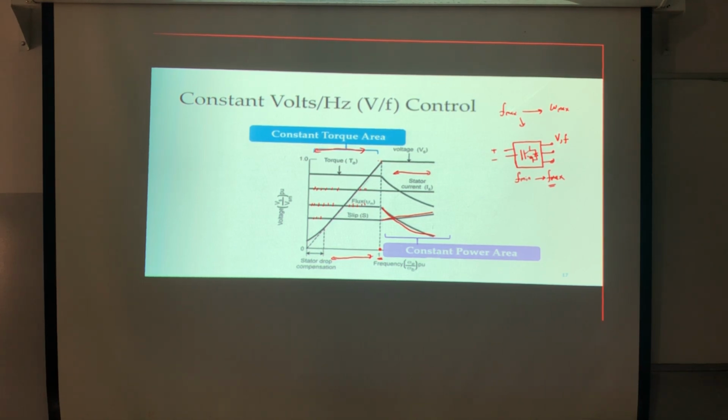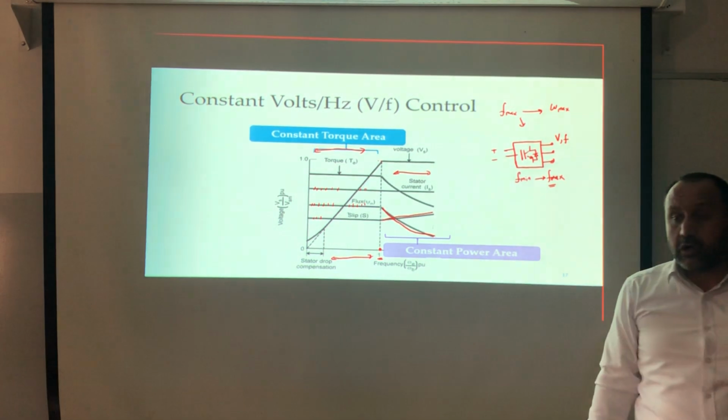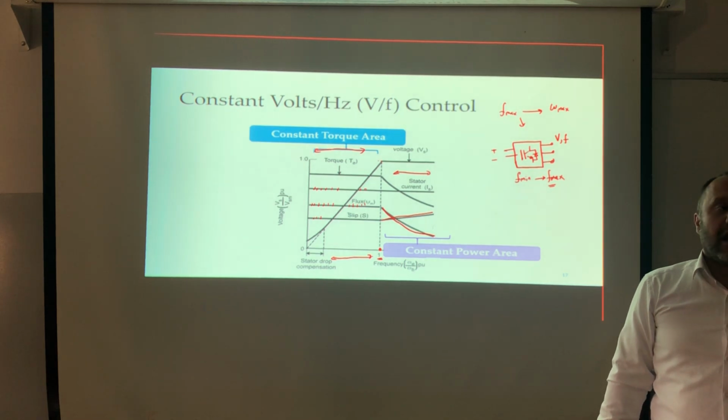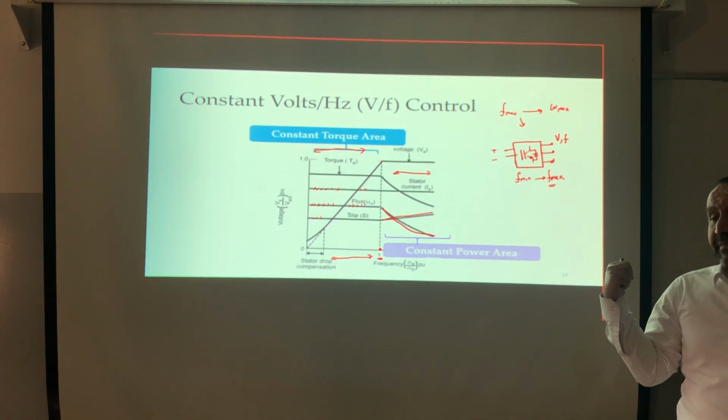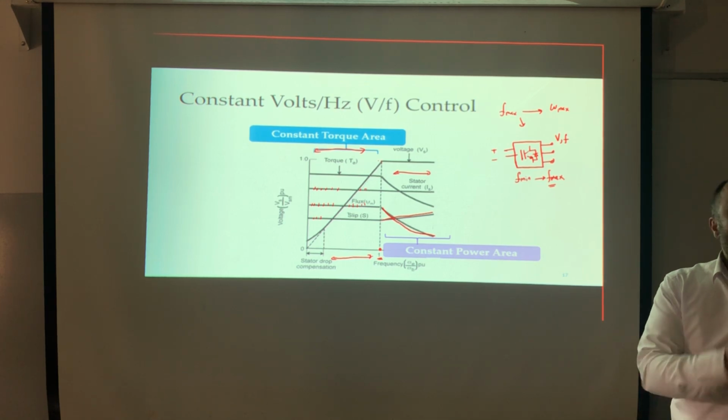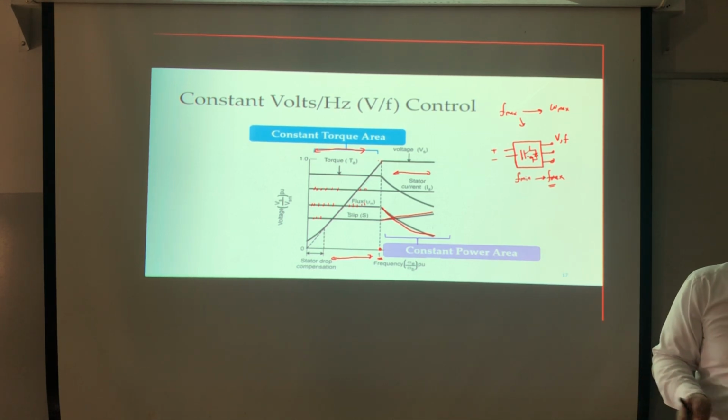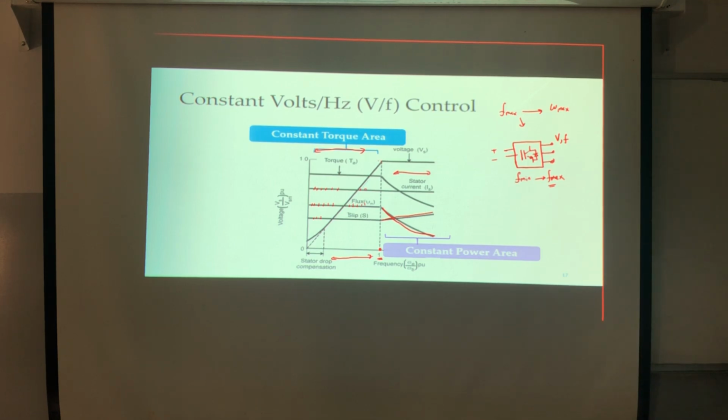At the end of the day, you cannot change the frequency without the inverter. Or, if the inverter allows arbitrary frequency, then F max is related to the maximum speed that the shaft can handle. In general, for us, I will restrict it to be the maximum frequency that the inverter can handle.